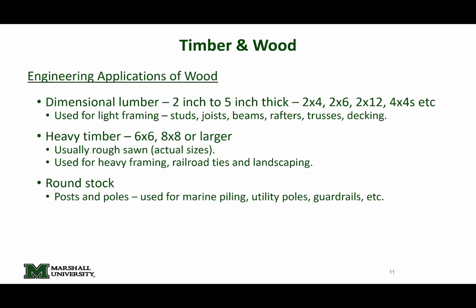Okay, and there is a reason, at least from a timber design perspective, why we delineate a difference between lumber and timber, and that's because we have different design stresses and whatnot that we use for those different components. We also have a separation for round stock, so like piles, utility poles, things like that, maybe some posts and whatnot.